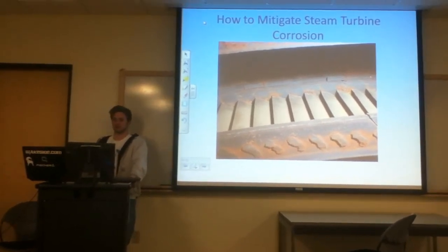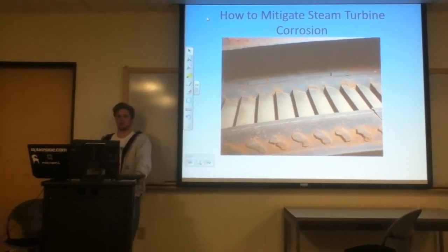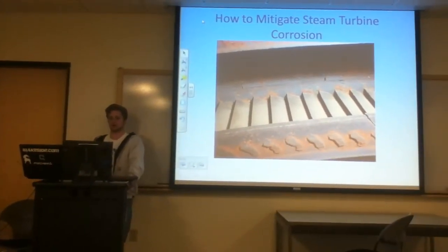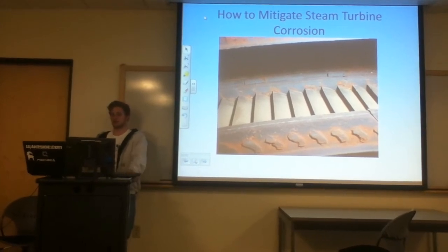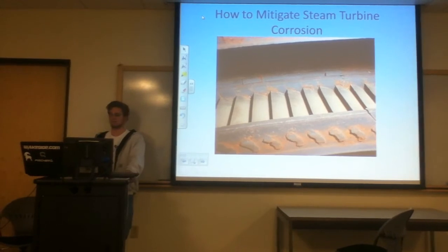Blades cannot be in resonance with the running speed. This will lead to high vibrations and greater stress, which results in more stress corrosion cracking. Also seen effective is washing the blades with chloride-free water on turbine shutdown.